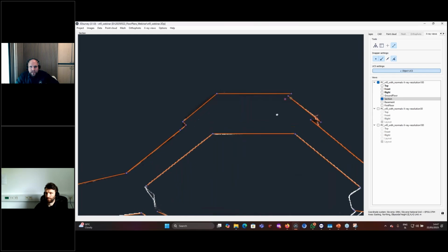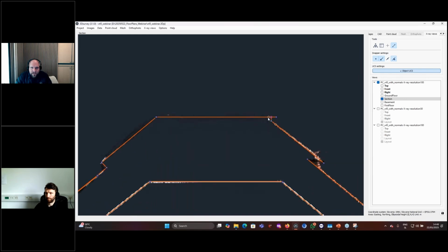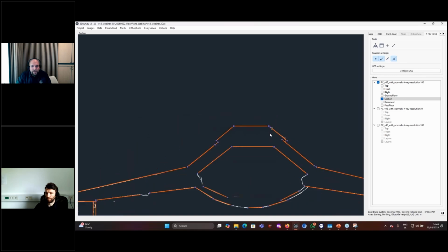Second thing, up here, I can make straight drawing to here. Then come here and let's do something with that. Now we'll just come in here and edit those two vertices. Disable the F8 to again disable this. And you see now it's snapping here. And now we will just move this one. I have to press escape to disable the draw mode and move it and snap on this one.